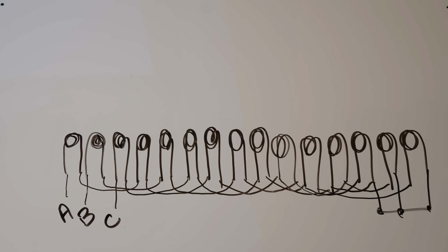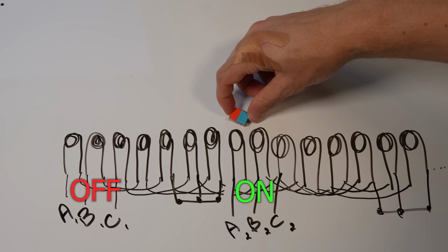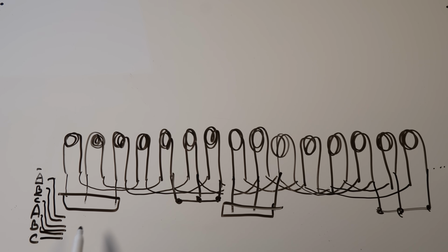As a middle ground, I split the coils into 6 zones. Each zone will turn on as it's needed and turn off once the train passes. To power these, I will need 6 signal lines. 3 will control which coil receives the high voltage, and 3 which receives the ground.